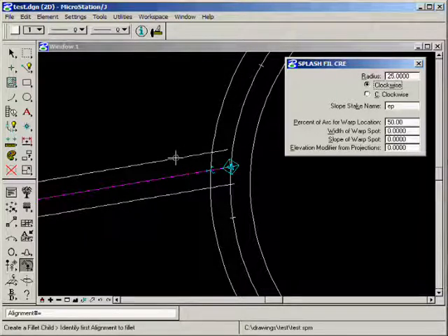However, that's not enough in road design. So it's also going to take a look at the cross slope, project the cross slopes, and then average those two cross slopes to keep the water off these roads. We'll explain a little more about that in a minute. Let's just demonstrate the tool.